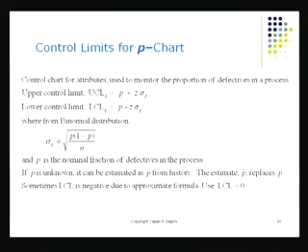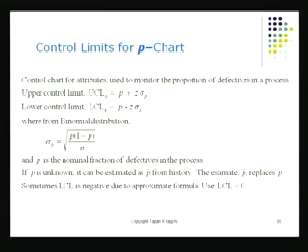So, we've got a lower control limit on the P chart, and that will be done as P minus Z times sigma P. How do I find the Z again? This Z value is from the standard normal table, and it gives you the cutoff point, the value of Z beyond which only a small tail of the normal distribution lies. And these of course have the assumption that the normal distribution is applicable in this particular case, like the distribution of defectives, for example, fraction defectives.